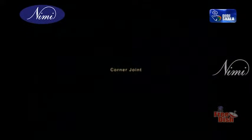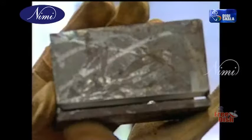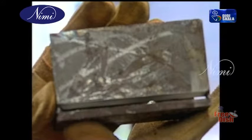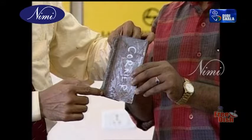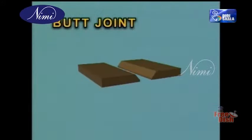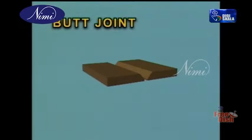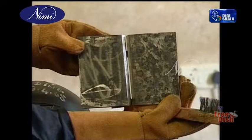Corner joints. In corner joints, one plate is placed perpendicular or at an angle to the other plate, with the inside corner edges of the plates placed together. Butt joints. In butt joints, one plate is placed adjacent to the other plate with a small gap in between, called the root gap.